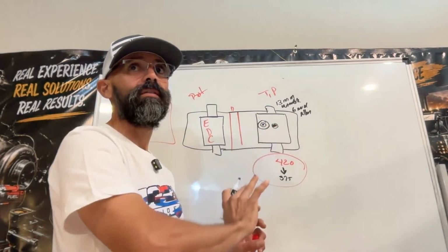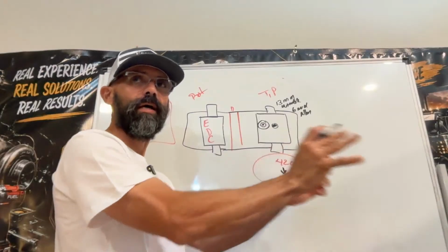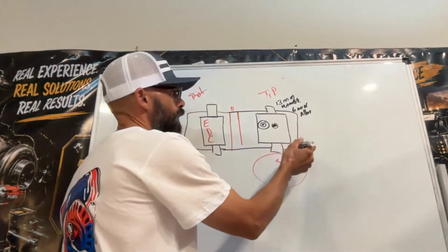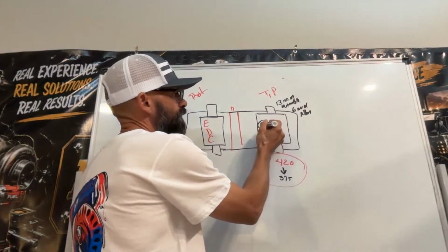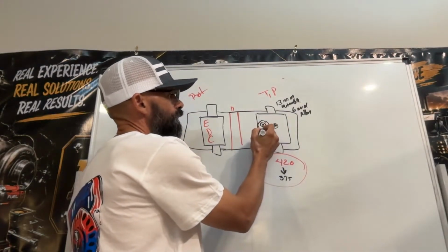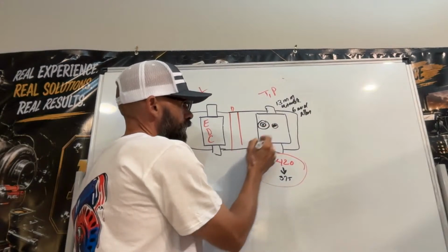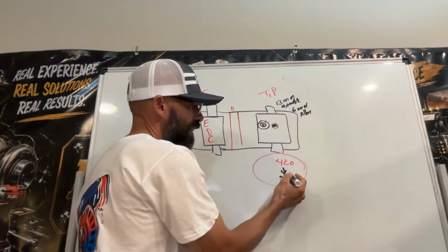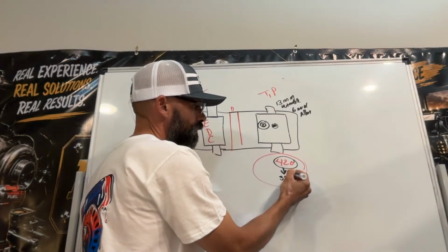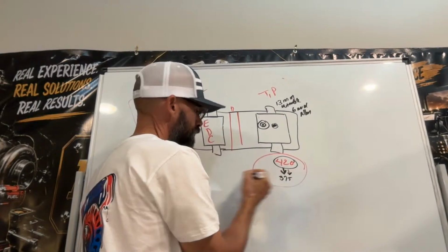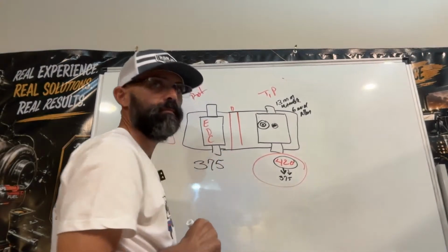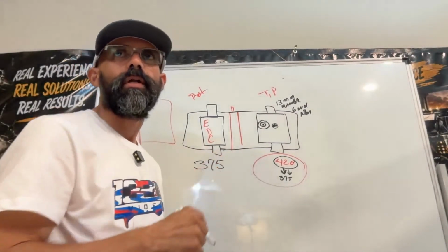This needs to be done at high idle because that's how the machine works. Keep that in mind. Once you loosen the jam nut, loosen the set screw, and you're gonna see how this pressure starts decreasing, equalizing to this pressure of the front section. That's all you gotta do.